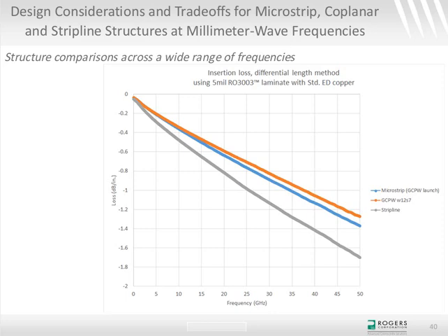Yeah, that's interesting. That's a good question, actually. If you put solder mask on top of the signal plane, of course, that's going to do something different. And if it was matched to the same dielectric constant as the substrate, I think that's going to cause it to be less quasi and more like a TEM wave, more like stripline, maybe. But to be honest with you, I really haven't dabbled with that. In theory, it seems like you could do things like that to make it less dispersive. I just haven't tried it. It seems fine theoretically.